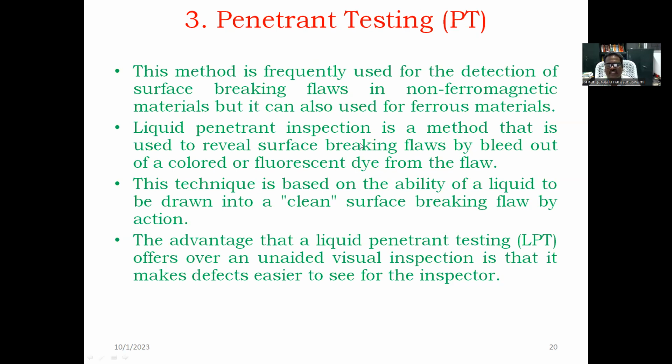Liquid penetrant inspection is a method that is used to reveal surface breaking flaws by bleed out of a colored or fluorescent dye from the flaw. This technique is based on the ability of a liquid to be drawn into a clean surface breaking flaw by capillary action. The advantage that liquid penetrant testing, LPT, offers over an unaided visual inspection is that it makes defects easier to see for the inspector.